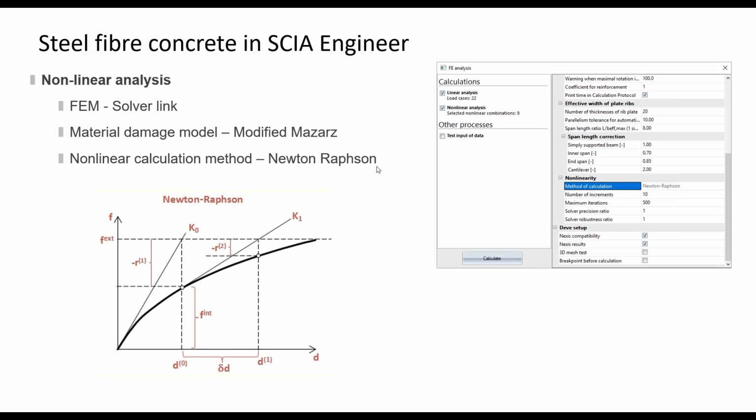Also, we're using the Newton-Raphson method for the calculation of nonlinearity. The user can increase or change the number of increments which should be applied on the load, and the user can also increase or decrease the number of iterations combined with the nonlinear calculation.